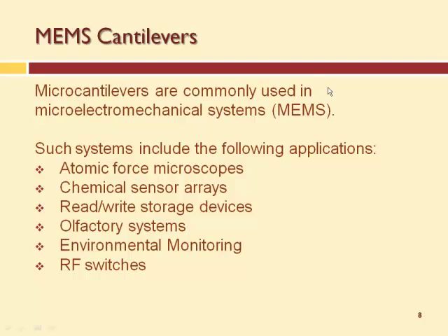Well, they're used in MEMS. Microcantilevers are used in MEMS, in atomic force microscopes. They have a cantilever with a tip on the end, and they drag the tip over the surface of a material. It's very similar, for those of us who are older and might know what a record player and a stylus are. The cartridge used to have a cantilever on the end, a little point that would ride in the vinyl track and vibrate and change that mechanical motion into an electrical signal in stereo or quadraphonic.